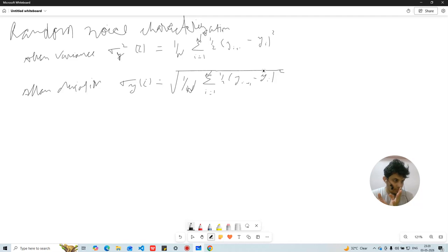Perfect clock, evenly spaced ticks. Real clock, slightly early or late ticks. That randomness is noise in time and frequency. Now, how do I explain the three tools? Allan variance, Hadamard variance, and phase noise.